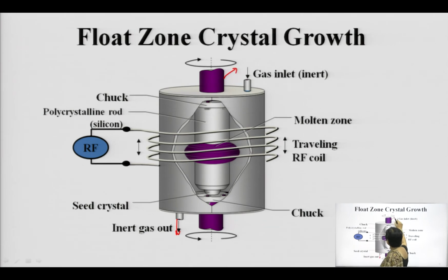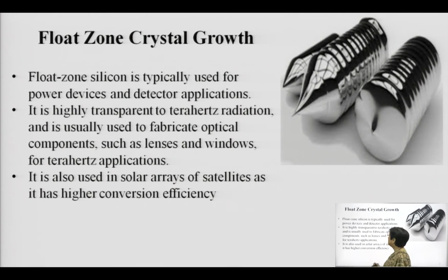The ingot is the same, the seed crystal is of the same orientation, or it is basically the product which is deciding the growth rate. Apart from the localization in the heating used for melting the silicon, most of the other parameters or mathematical analogies are almost the same. The only thing is, since the crucible is not being used, there has to be a lot of precision involved in pulling the seed crystal, because the area is confined.